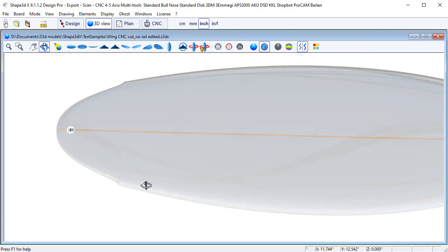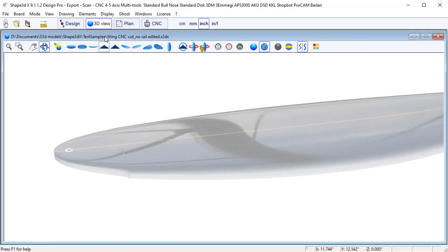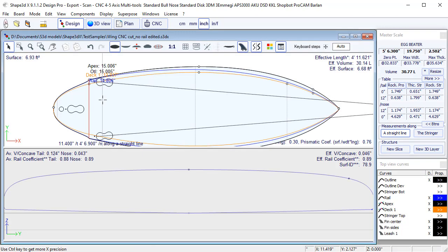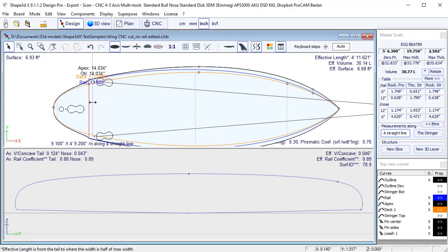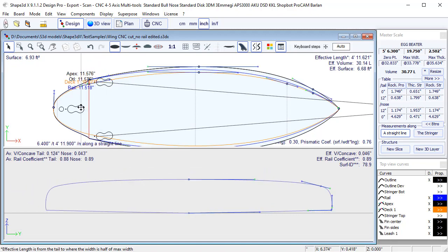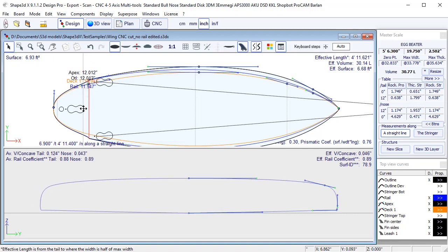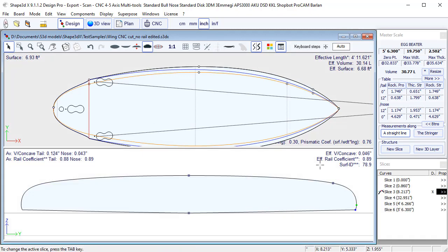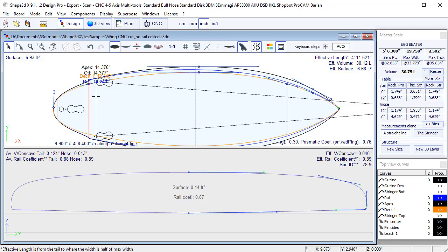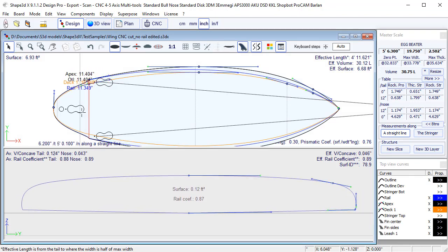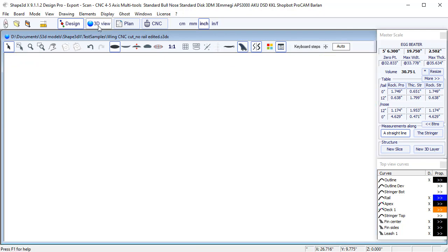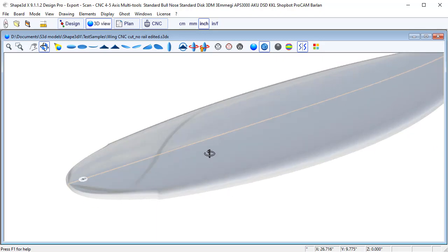And if I look at the 3D, you see it's better, but you still have a very small step. This is actually due to the fact that this tangent here is continuous, and you have the constraint of this continuous tangent. I can press the T tab to see the tangents. So you see that the kinks of the rail will spread on the deck because the tangent has to be straight. So if you set this tangent as angular, then you don't have the continuous constraint anymore. And then you allow it to do a small kink when you go to the tail, but then you separate the deck from the rail on this section, and you get a perfectly smooth deck.